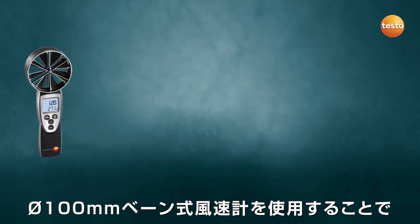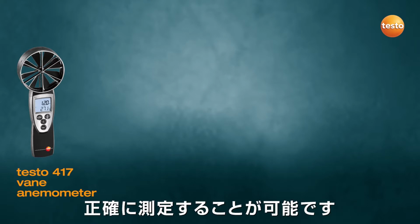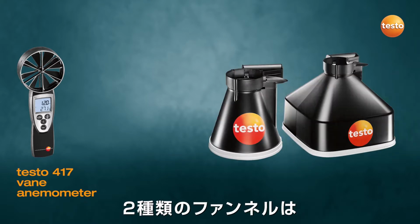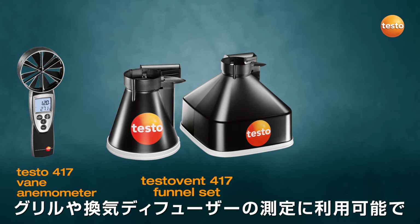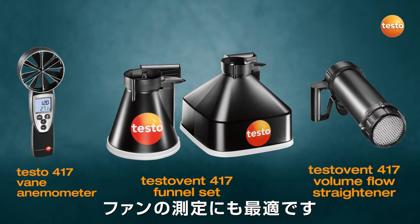You will be perfectly equipped for taking measurements at supply air and exhaust air outlets of a room ventilation system with the Testo 417 vane anemometer. It can be combined with two funnels, allowing volume flow measurement at grills and diffusers, and thanks to the TestoVent 417 volume flow straightener, it is also suitable for swirl outlets.